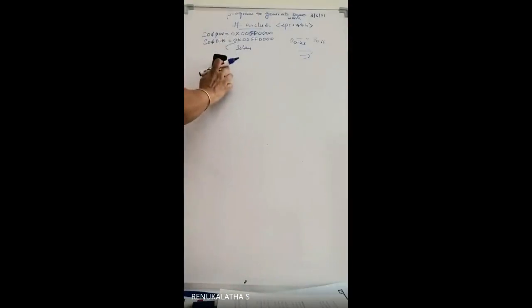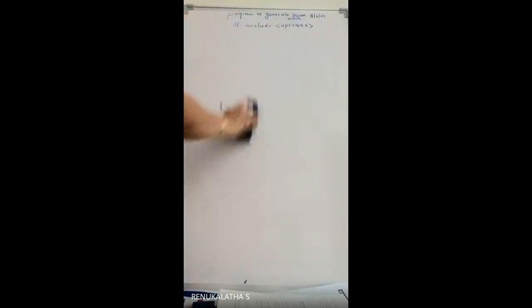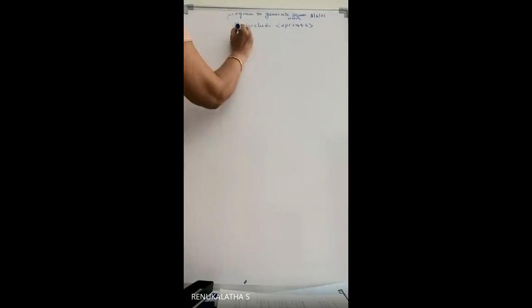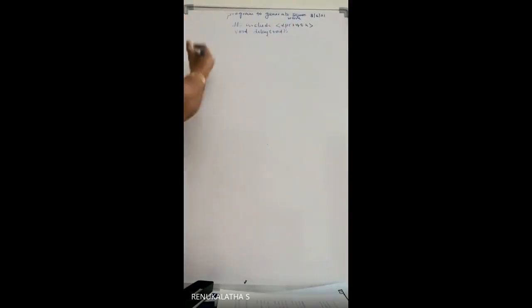Then you have to write the delay subroutine function. So you will be calling the delay function, hence you declare that. void delay(void); this is a declaration. You are not defining a function here.